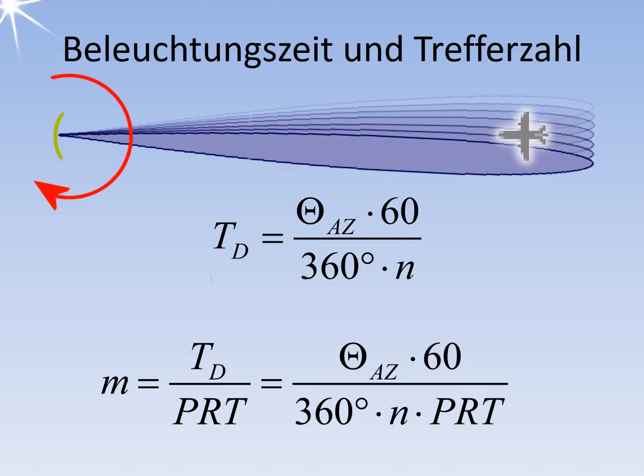An air traffic control radar using the sliding window method for bearing angle determination requires about 18 hits. Many radar sets use pulse integration in radar signal processing to distinguish target signs from noise and interference pulses. If the number of hits is too low, this target sign can be lost by the increased threshold values due to the interference.